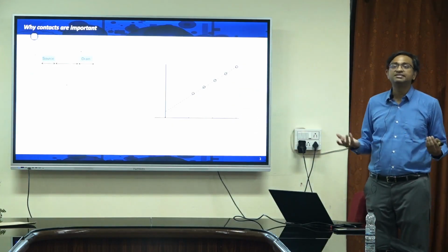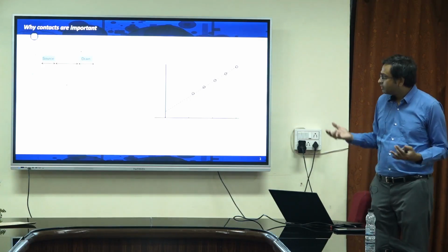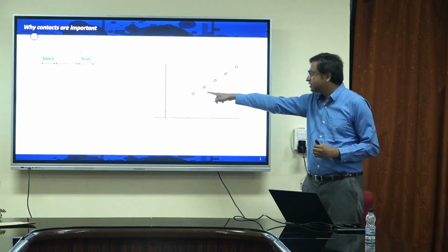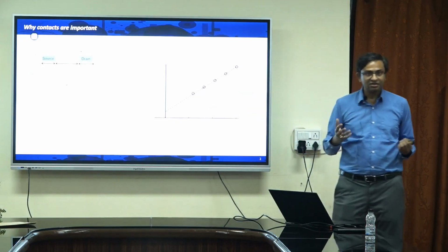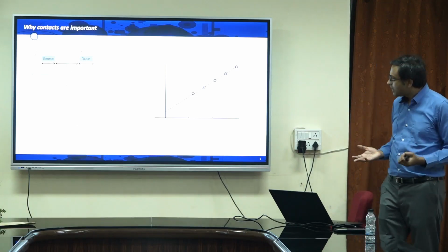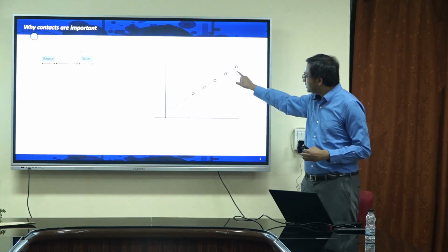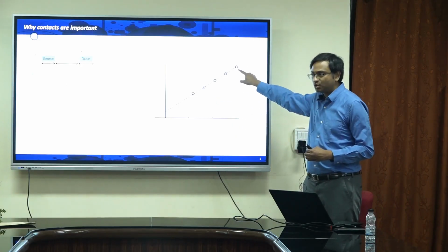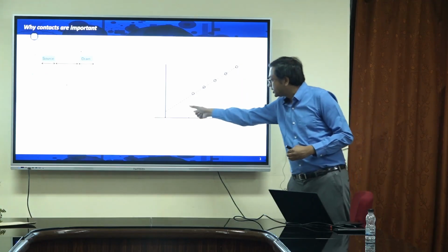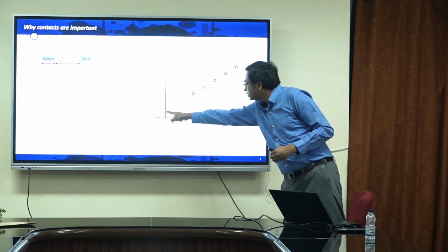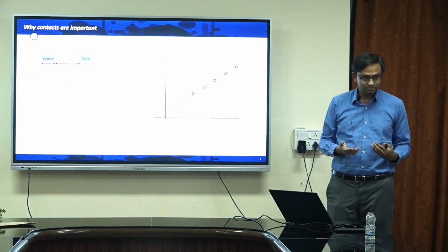and what will happen when LCH is 0? Channel resistance will be 0. But then you see the total resistance is still not 0. Why? Because you have a finite contact resistance, correct. So now you see that when my device is very long, my contact resistance does not play an important role, because my channel resistance is very large. While when I go to a very short channel device, your 2RC, the contact resistance, becomes dominant.